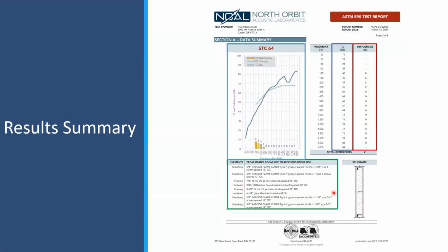So gauge is the way a lot of us still tend to talk about stud metal thickness, but the actual steel framing industry moved to using mill thickness quite some time ago. I think like a decade or 2 decades ago. Just the rest of the world really hasn't caught up to that. It's important though to talk about mill thickness instead of gauge because over that time we've also moved towards using sort of equivalent gauge studs where they use a thinner steel,